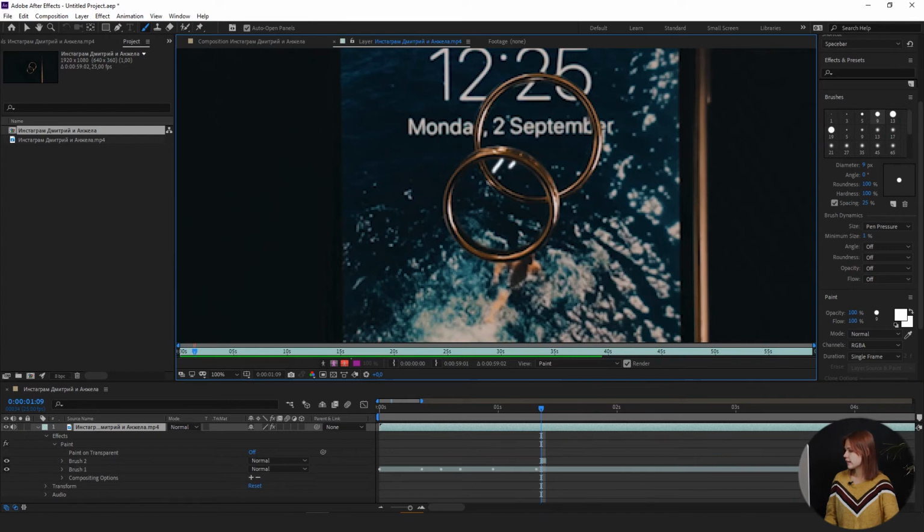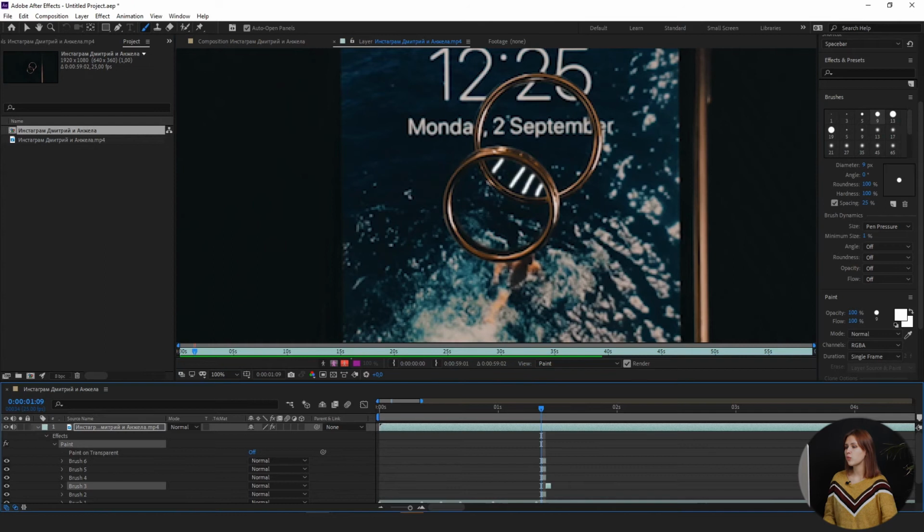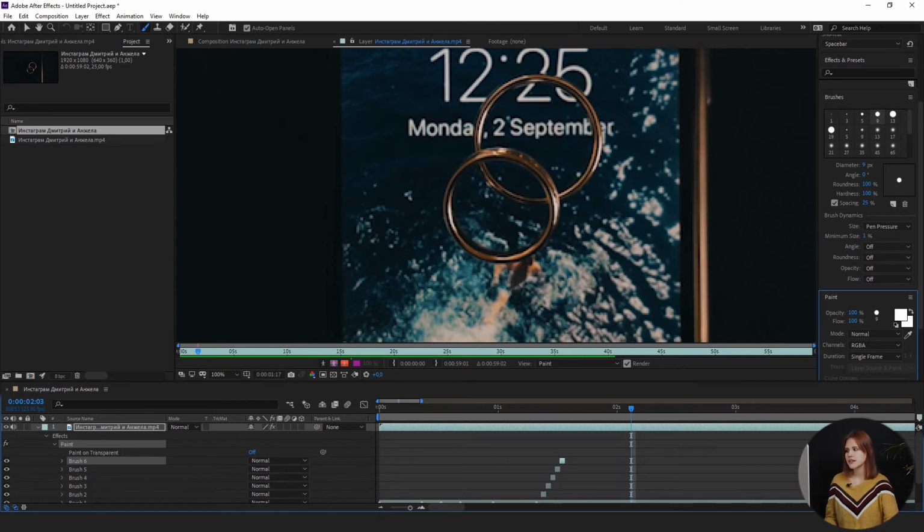We draw lines and we have 5 new strokes. We will place them on the timeline one after another. The animation is swift. If we need it slower, we can do that by selecting the last one, custom duration. When custom duration is selected, a keyframe parameter appears to the right of the graph.